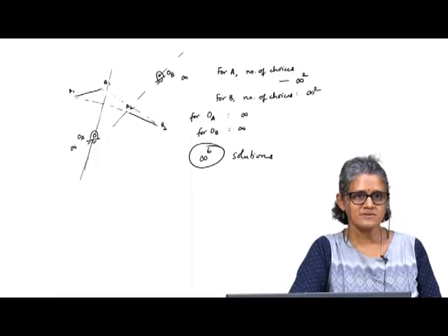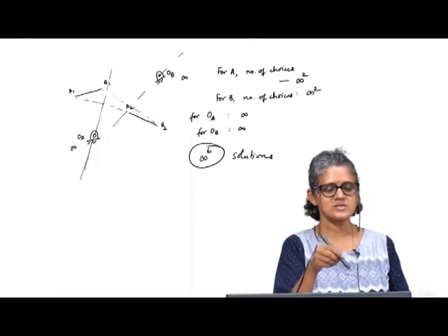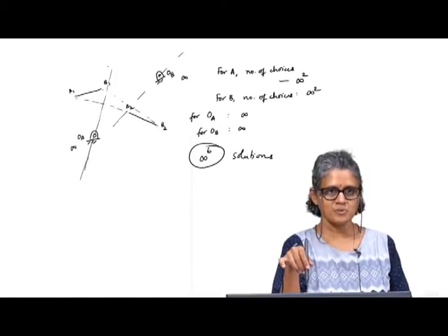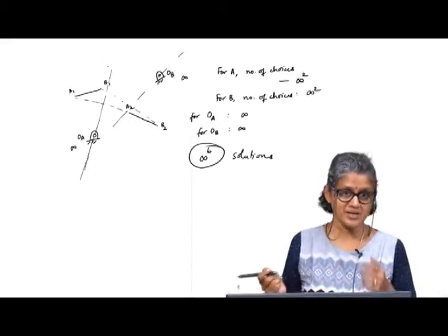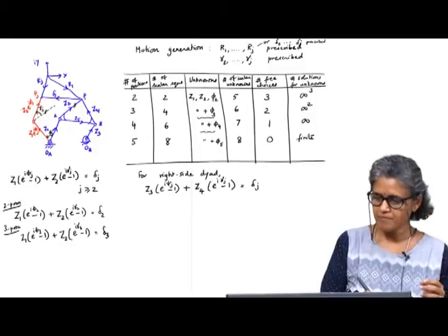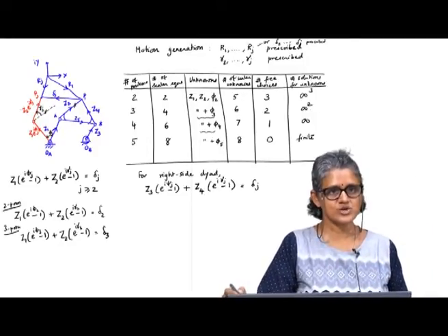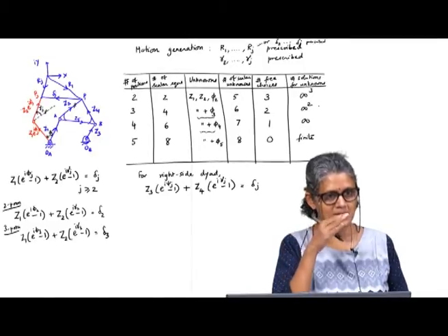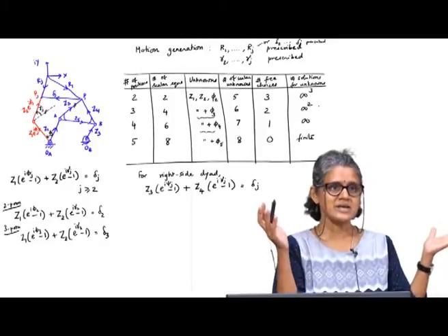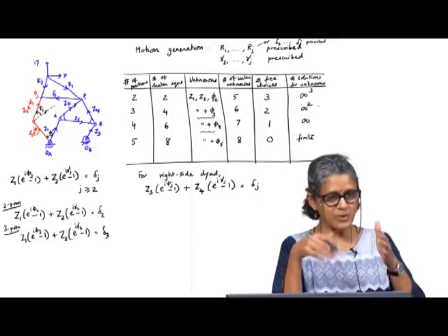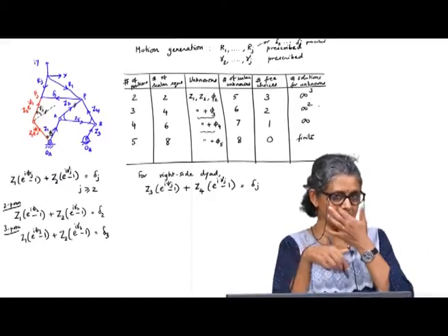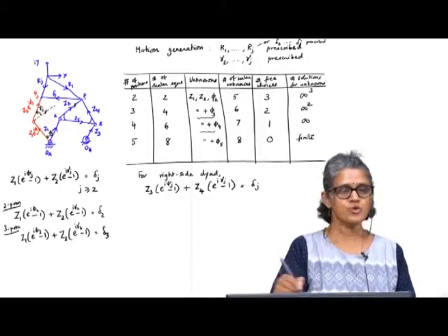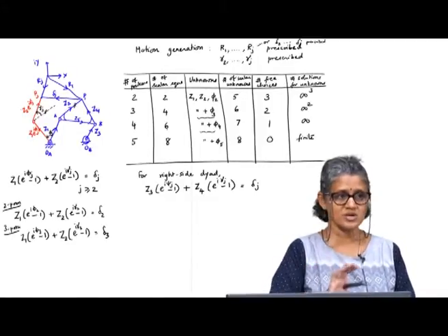What may be restrictive is how you can find the solutions, because if I am trying to do geometry, like for the 3 position problem, we ended up with a unique solution, although I actually have infinity square choices for the 3 position problem. But because of the way we do the construction, when I choose a point I immediately lose 2 free choices. When we do it analytically, you will see I can possibly choose an angle or a length perhaps, when we look at solving these equations. That gives you more flexibility, but the number of free choices does not change.